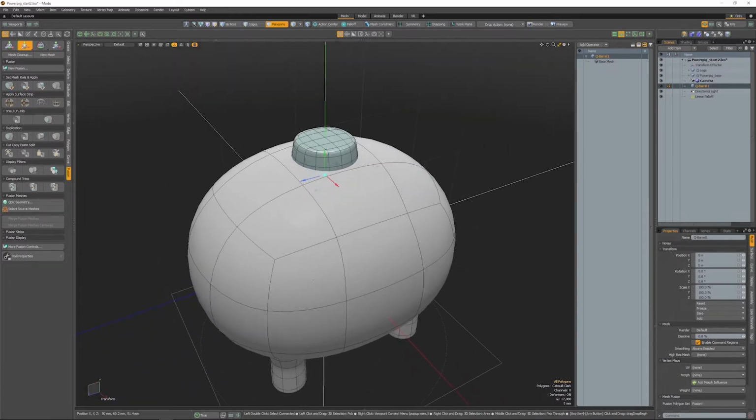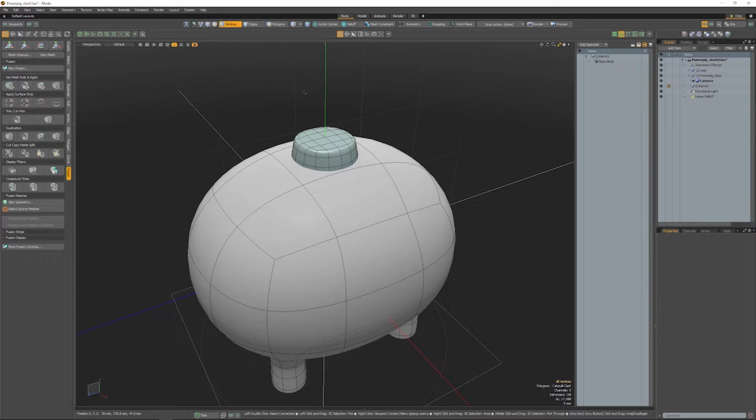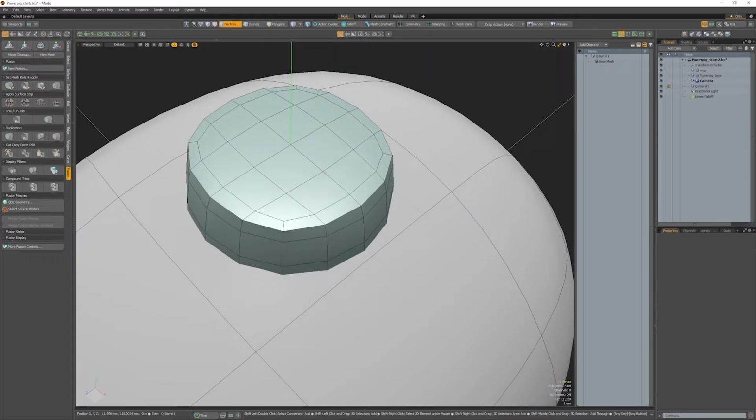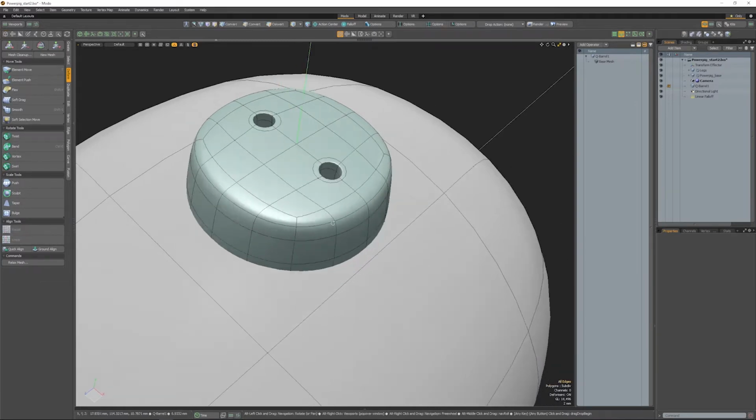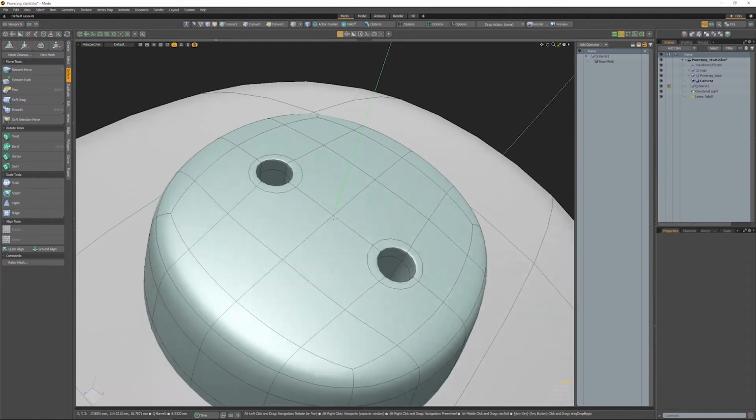seems alright. So now I can come here to the vertex, select these two, and B for bevel, convert to edges, and radial align, convert again to polygons, B for bevel, pull down, convert again to edges, B for bevel. I didn't need to convert this one. I could bevel with polygons, but it's okay. Edges, B for bevel, and that's it. So subdivide, and it's alright.